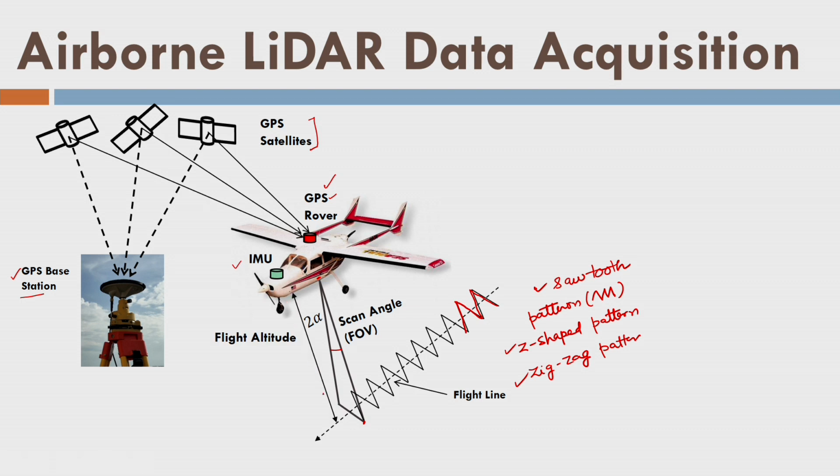Okay. So this is the flight altitude of my aircraft, which is shown by the arrow here. Now this is the swath, which is the width of this data acquisition across the flight line. So this is the flight direction here, or what we call the direction of flight line. Now this 1.5 meter here is showing you the spacing of the 2 data points here and here.